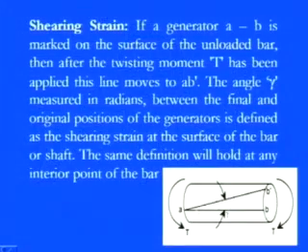So as a resultant, in this stabilized manner, we find that there is a distortion, and as we compute it in terms of shearing strain, the angle clearly gives you the kind of distortion. This angle is known as the shearing strain angle, or we can say that B dash is nothing but equal to the shearing strain. So this is the real significance of shearing strain.